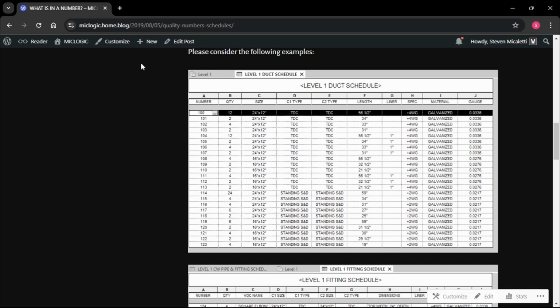So you can box the whole floor, or just an area, level 1 area A, number it all together, and send it to the shop. When you send it to the shop, it's going to be in a manageable chunk. It's going to give them all of their gauges put together, all of the connectors put together, all of the insulations put together, right? You're not switching from lined to unlined. You're going to build all of your 22 gauge unlined, and then build all your 22 gauge lined.